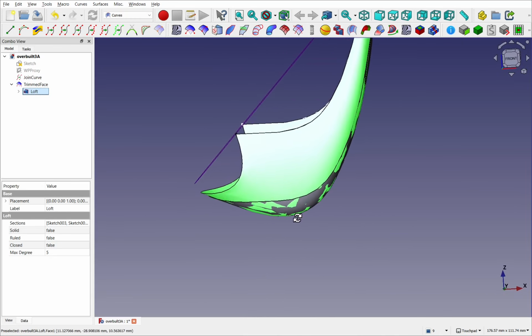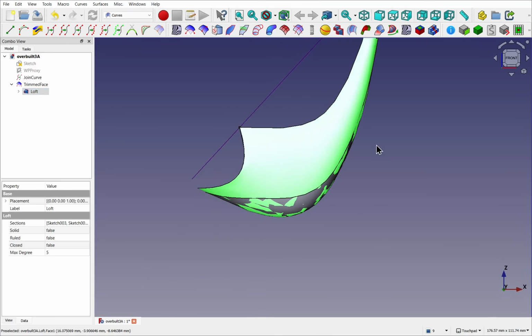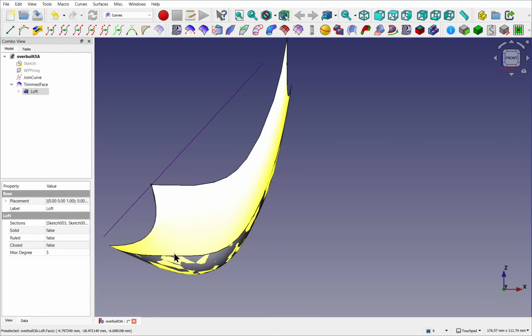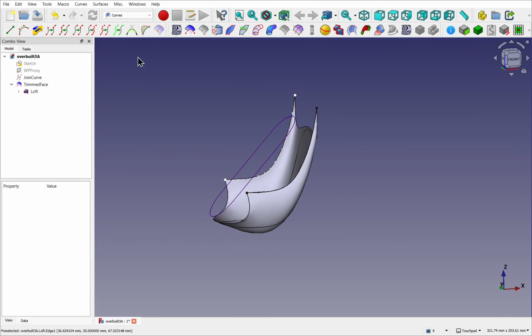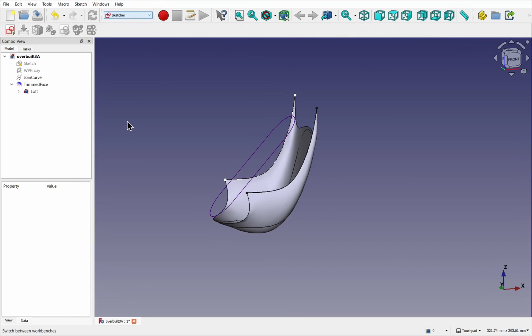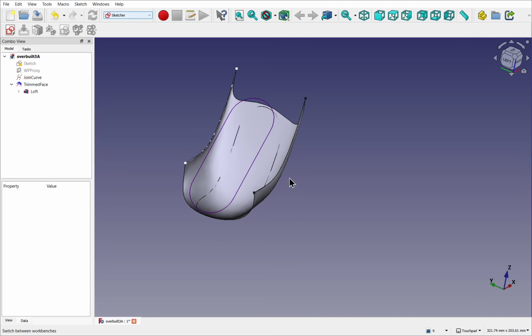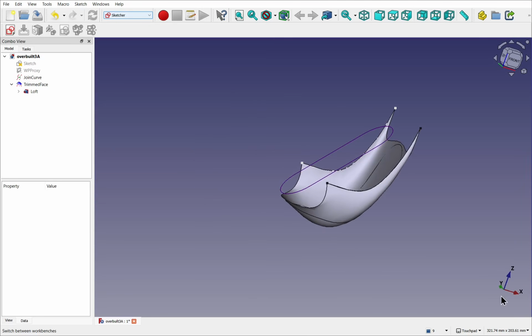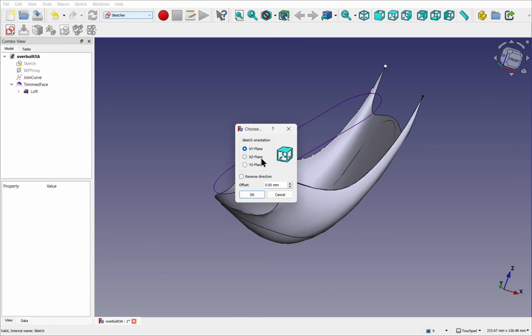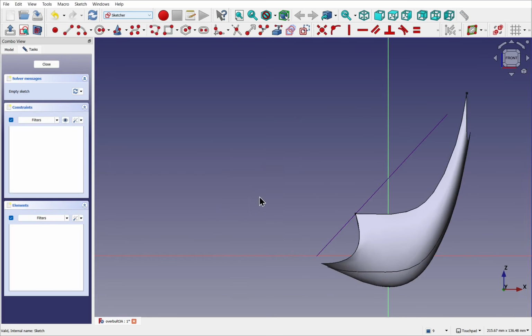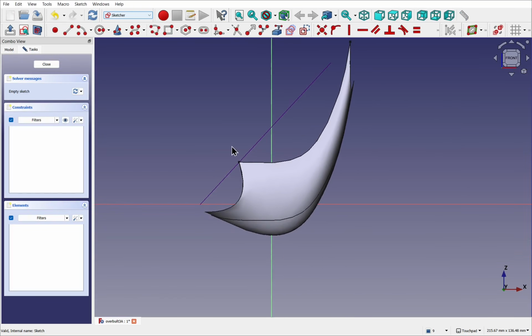And let's say, from this position, I want to create some tabs that come up here. We just use a basic rectangle for that. Come over to the sketcher and we'll create a sketch. Make sure nothing's selected, because I'm going to create a sketch using the basic planes, the XZ plane. So let's create a sketch along the XZ plane and hit OK. You see that there.